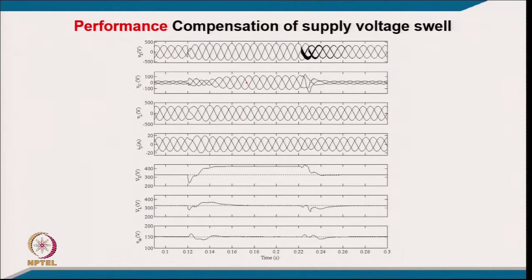This is the injected voltage, and after injecting this voltage, the load voltage is regulated, sinusoidal and balanced across the load. Thus the load is not affected by this particular swell also. You can see how the RMS voltage behaves during the swell and after it, and how the load voltage and DC link voltage are regulated.